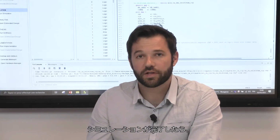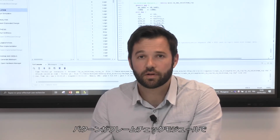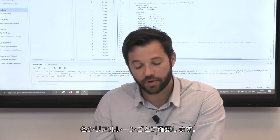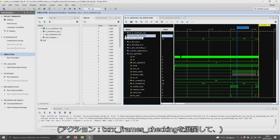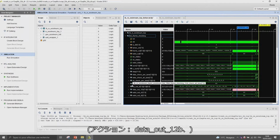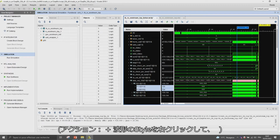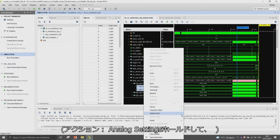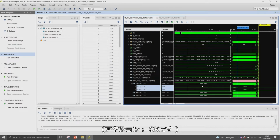Once the simulation has completed, you can check for each serial lane that the ramp pattern sent by the ADC emulator has been received properly in the frame checking module. So I can expand the frame checking module and the receive data, and display for each serial lane the ramp pattern sent by the ADC emulator in an analog view. We can see here that the ramp pattern is received properly.